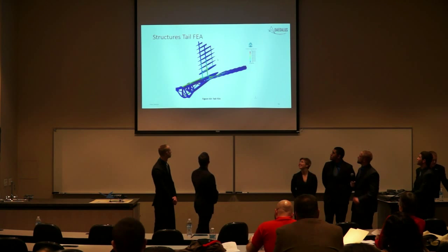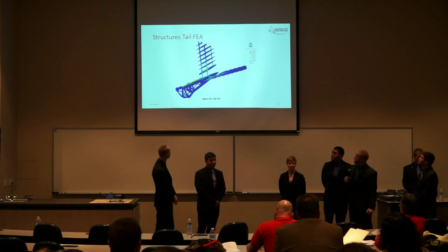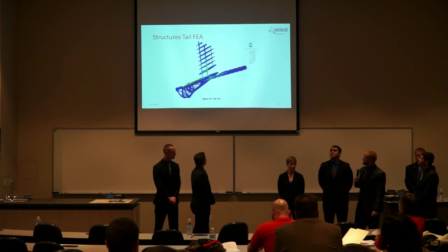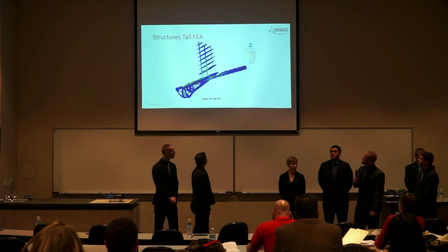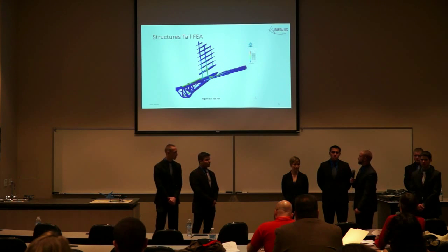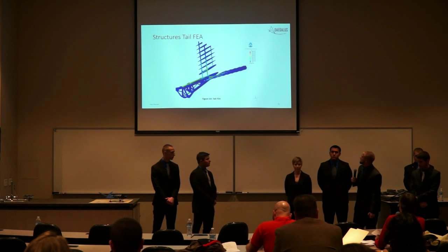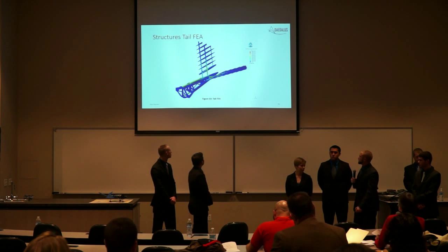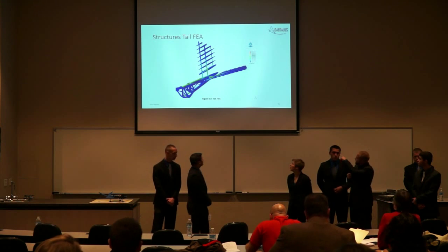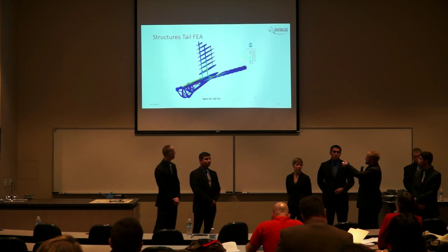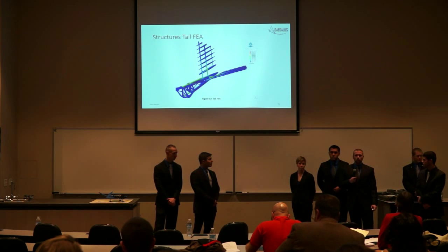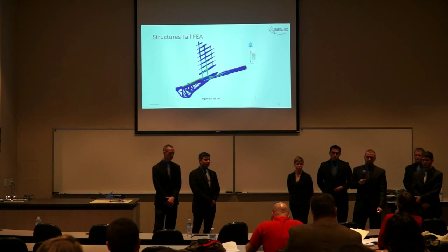There we go. So we did model the V-tail, or the tail of the YB-3, using our finite element analysis. For these forces, we generally just use the moment to create turning for both takeoff and landing of the aircraft. As you can see, there's a maximum stress of about 33 KSI that happens where that pin is located in this green area. And what's your margin of safety then for that? 1.5. Okay, or factor of safety.